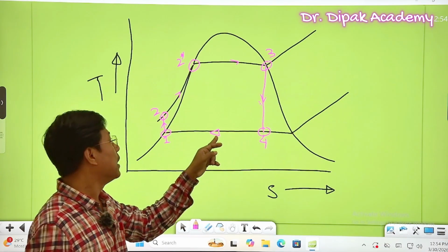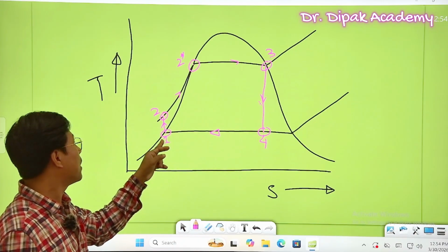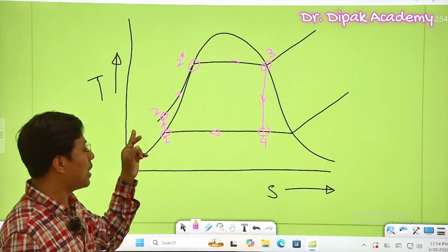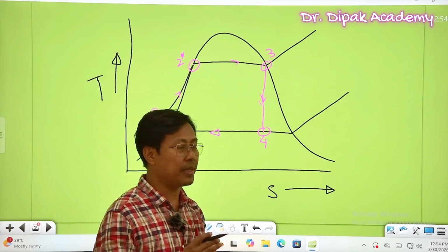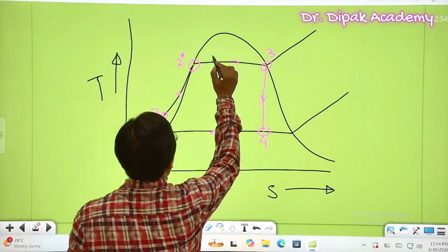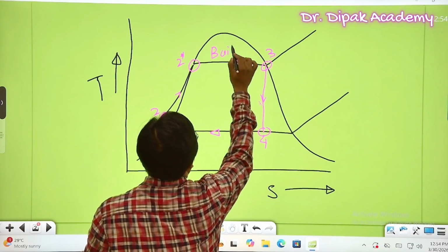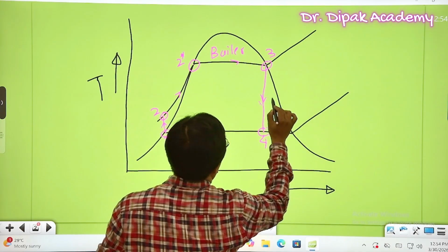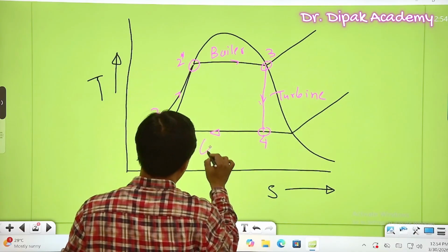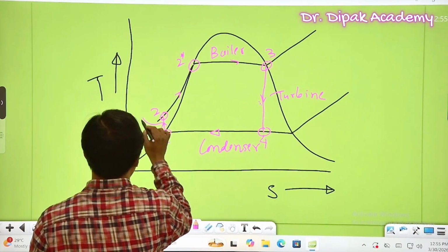It will be condensed inside the condenser, and then again it will come to point 1. So in this way all four processes are taking place so that a complete Rankine cycle is carried out. So simply we can write here: it is the boiler, here it is the turbine, this is happening inside the condenser, and this is the pump.